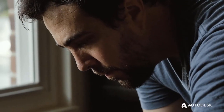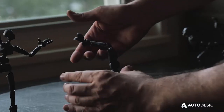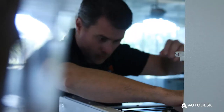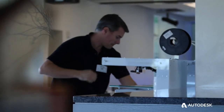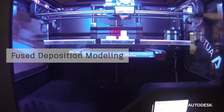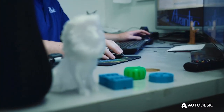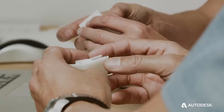For hobbyists and makers, additive manufacturing is very accessible with low-cost machines that deposit relatively large layers and use plastics like ABS and PLA. These are usually fused deposition modeling, or FDM, where the plastic is pushed out of a heated extruder, and lower-end FDM machines often do not support material. Additive manufacturing services for those who do not want to invest in an entire machine are also available.